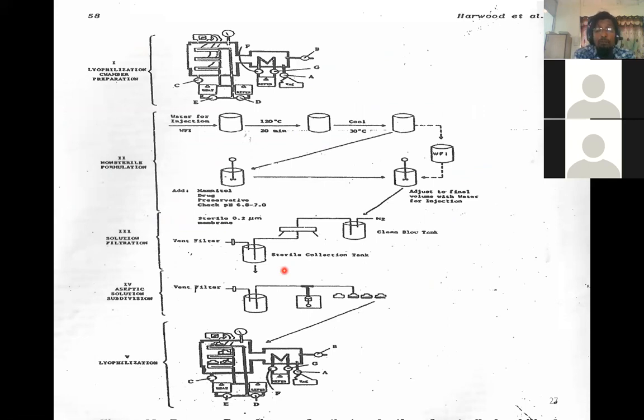I hope you remember, from second year in pharmaceutical engineering we have already studied how freeze dryers work. So for those substances which are thermolabile, which can be destroyed, deteriorated and degraded when temperature is increased and dried, we can go for the freeze drying method. This is also called lyophilization. Here basically water is sublimated, right? That is, we don't go for a drying step by heating, but instead we go for cooling, and the triple point temperature is generally used here to attain this lyophilization.